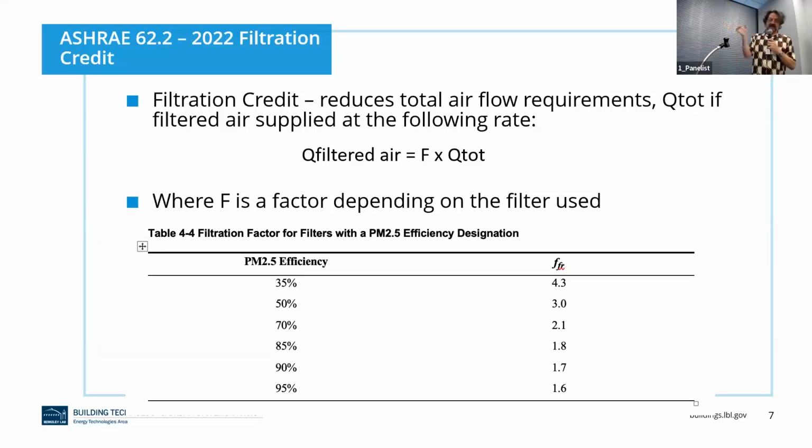And ideas like this are sort of blurring that line between air quality and energy use, because a big part of the energy use is heating and cooling and controlling the humidity of the air we bring in and out. If we can reduce that because we filter some, then maybe we can have a more energy efficient way of getting to acceptable indoor air quality. And that was part of the rationale for this sort of approach. So to be clear, this isn't in addition to providing the airflow. This is a substitute for.